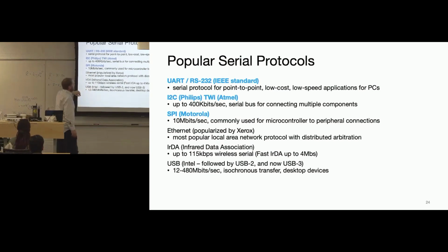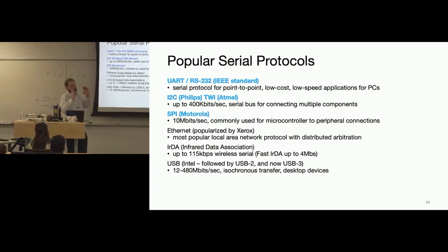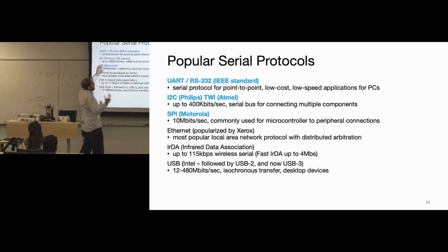SPI, serial peripheral interface, doesn't actually have a standard associated with it. It's much more free and open as a standard. When I say there's no standard associated with it, there's no IEEE, no governing body that controls SPI. It's more of an agreement between all the manufacturers on the common interface modalities, and sometimes you find weird devices that don't implement one of them, and they don't have to because it's not beholden to a particular standards body. And these are other ones we're not going to talk about.